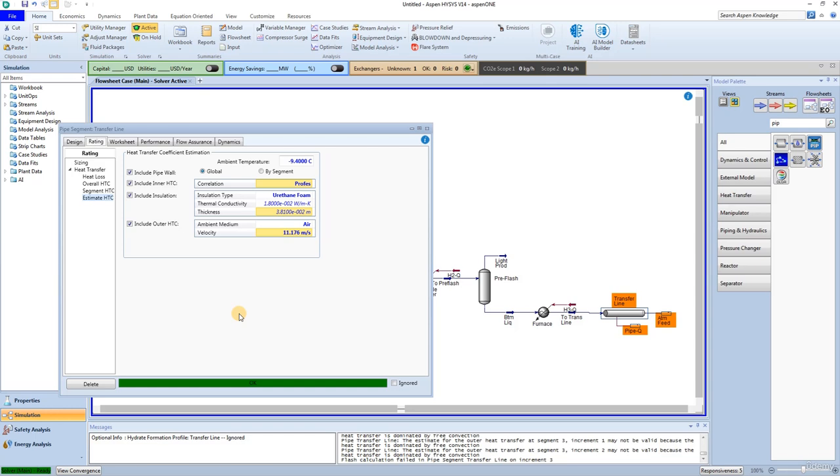This allows the process simulator to quickly and easily judge the viability of a pipeline over time based on whatever fluid is being modeled. The particular flow assurance calculations that can be performed are as follows: hydrate formation calculation, rate of corrosion due to CO2, erosional velocity, slug flow analysis, and wax deposition.